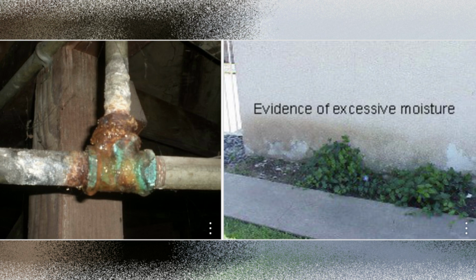Check out the attached photos. As you can see on the left, we've got a leaky pipe in a crawl space. It's pretty easy to understand how we would have problems with things like millipedes and centipedes and other insects that require a lot of moisture when you've got a constant drip from a pipe. On the right, you can see where gutters are spraying up against the foundation of this home. They're just putting a ton of moisture right on that foundation. So, of course, in periods of drought, ants and things are going to be attracted to that area.